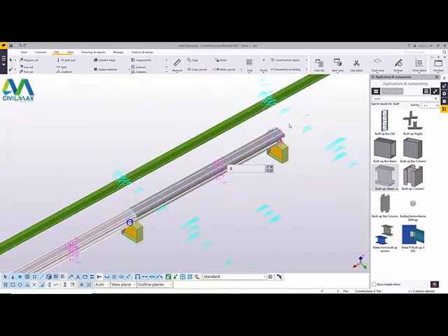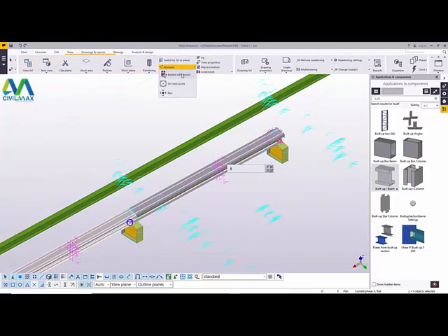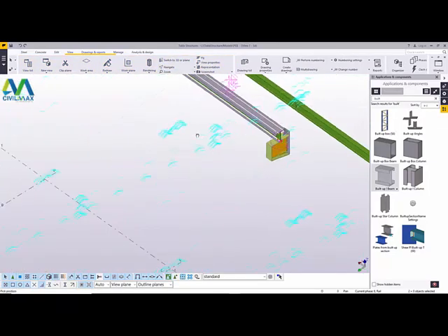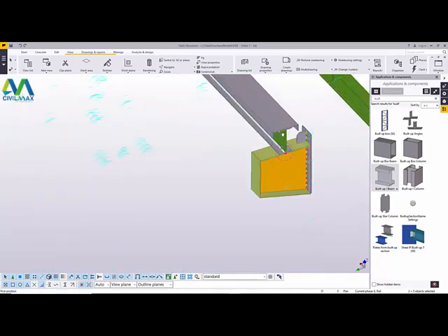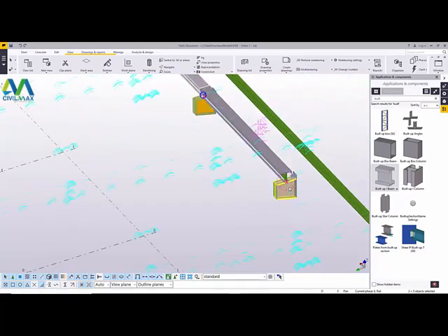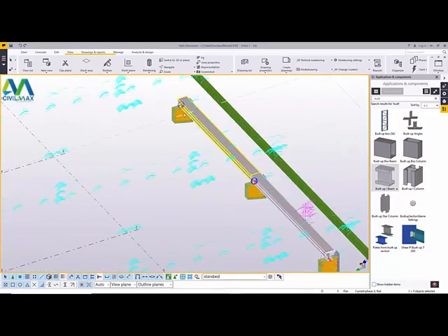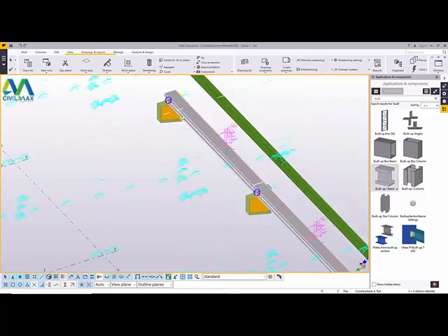So once that has been done, we'll come to View and pick on Navigate. Remember, that's my option of rotating my model. Here we have the options that I have explained to you. So whichever way you find yourself comfortable, just follow that process. Right click. Just make sure you pick the component you intend to copy. Don't pick anything else. I'll pick on that.